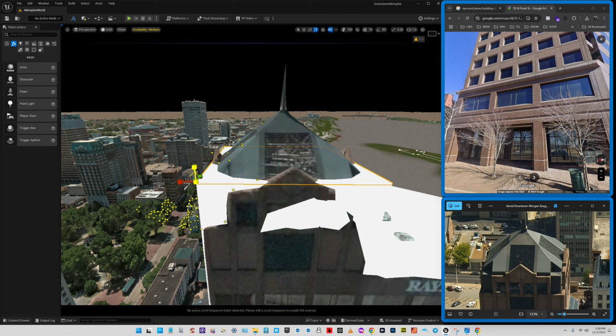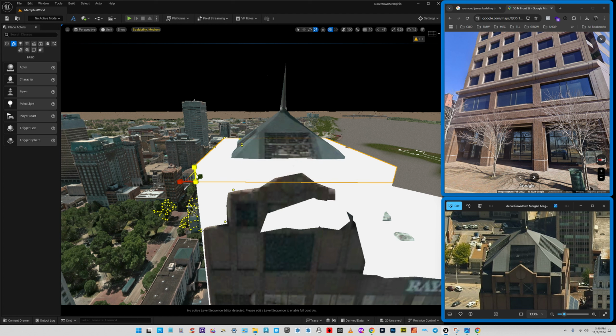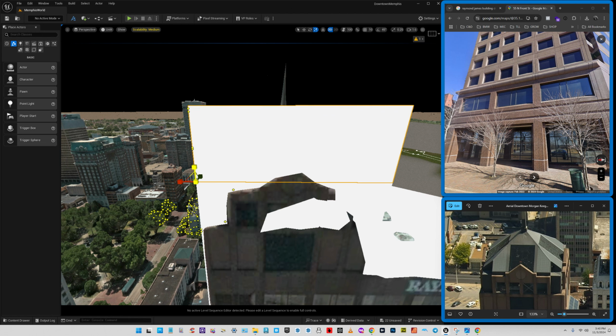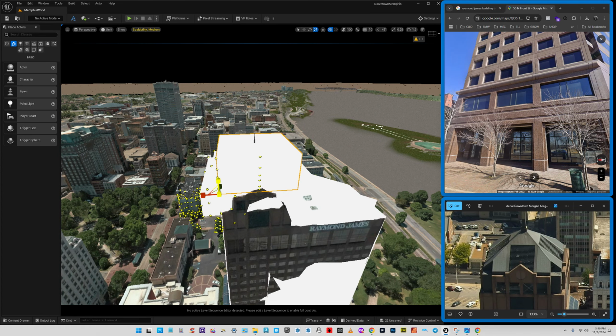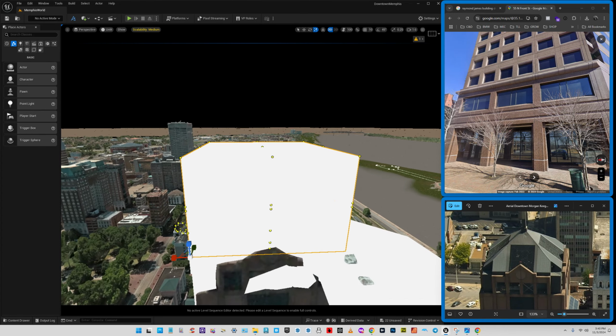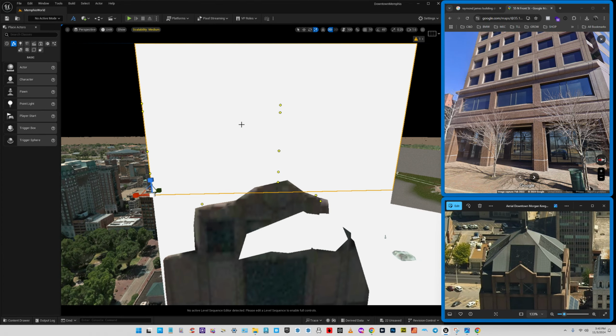And maybe actually instead of using the tip, man, the proportions of this are okay. Yeah, I think that's fair. I think we can do the tip of that so that we can get the height of that tip correct inside of SketchUp. I want to duplicate this again right where it is, but then pull this one up to maybe the tip of this, and then Control D to duplicate again, and we're going to keep those three overlapping and pull it up to the very, very tip there. All right, and that gives me enough information to use, I think.